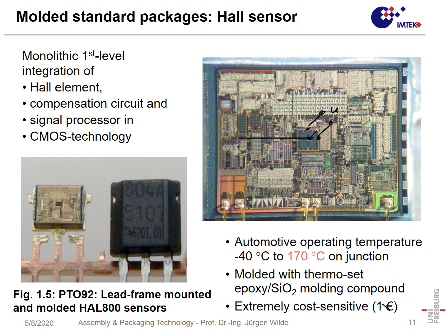After the signal is digitized, the signal is processed, and after the processing, the signal is reconverted again to an analog signal. So let's say a magnetic field of 0 to 100 millitesla is proportional to a voltage of 0 to 5 volt.